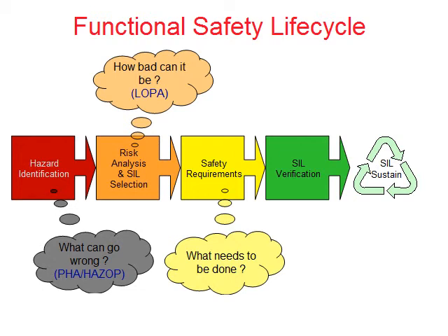Well, you want to be specific enough and define the areas and define exactly the operational parameters, so when the safety function is designed, you can then go and verify that it's achieving those levels of risk reduction and those performance requirements.